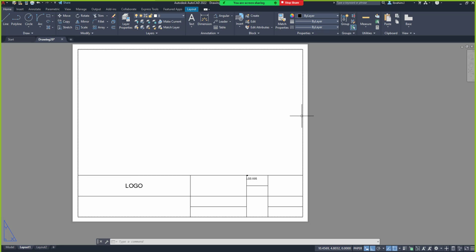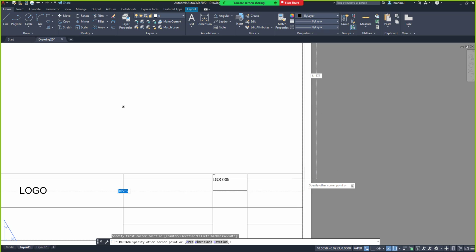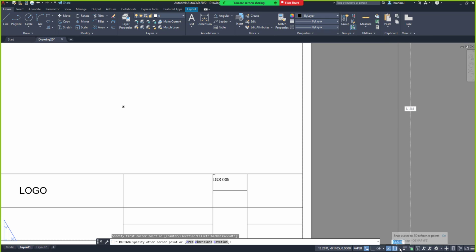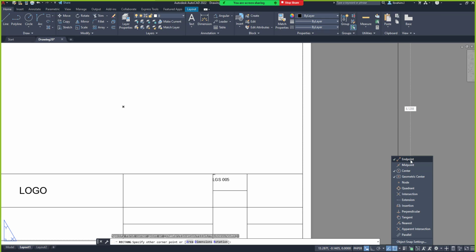So what do I want to do? I've created this design here. Yeah, right? We all know that what I need is this viewport that is right here, right? So what I can do again is create my rectangle, and then that same point I'm creating my viewport around here. But because my endpoint is on, it will start giving me that error message. Meanwhile, I don't want my endpoint to be on, or midpoint or whatever here. Just want to place at the intersection.